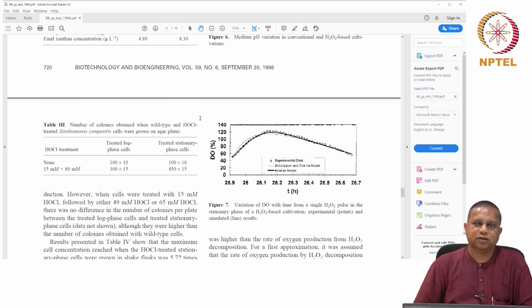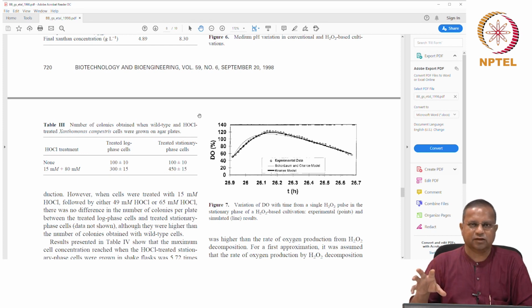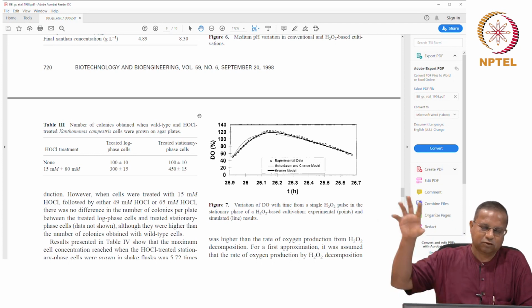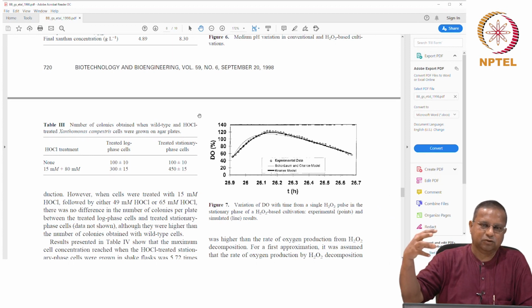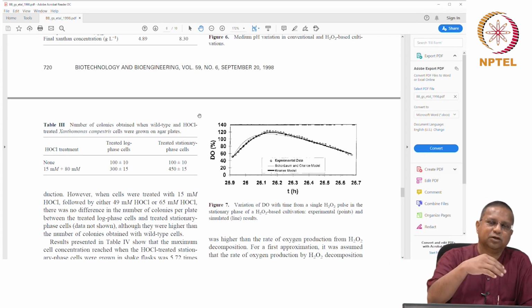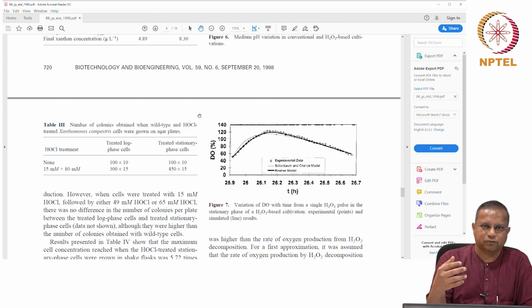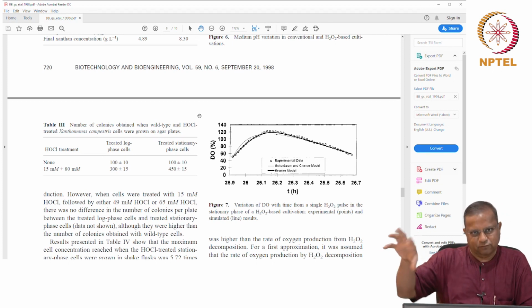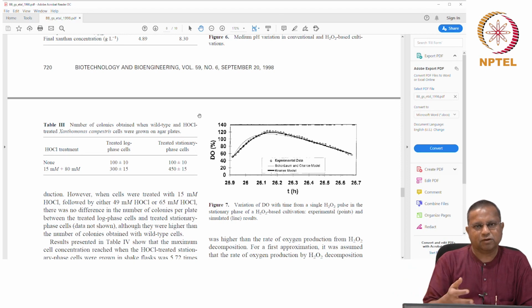We also worked out the costs that are involved, and if you consider everything, the cost per kilogram of oxygen turned out to be 15 paise compared to about 2 rupees per kilogram when you consider aeration as a source. Why? Although air is free, you need to go through appropriate filtration, appropriate sterilization, and so on and so forth. And that is expensive. And of course the compressor costs are there. There are no compressor costs here.